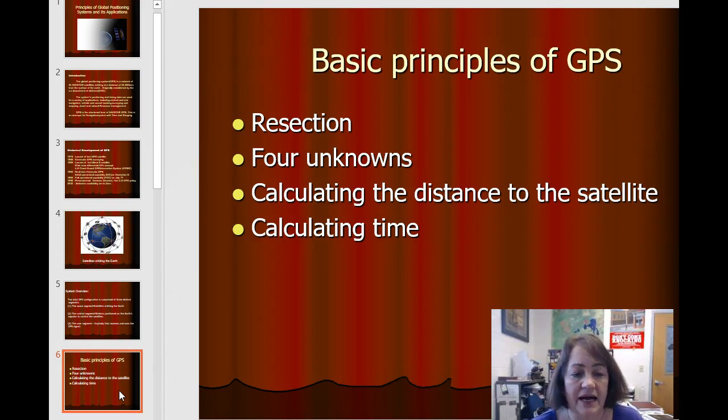And because of that, what we're really dealing with in GPS is at least 4 satellites to get X, Y, Z, and time. Sometimes you need more. And it sort of depends on the position of the satellites compared to the position of the receiver. But like if everything's straight over your head, you don't have a good spread, and you can't get a lot of distinction between elevations. So you may need more than 4 data points, but you need at least 4 data points in order to calculate 4 variables. It's just basic principle of algebra: 4 equations, 4 unknowns. So X, Y, Z, time, 4 variables.